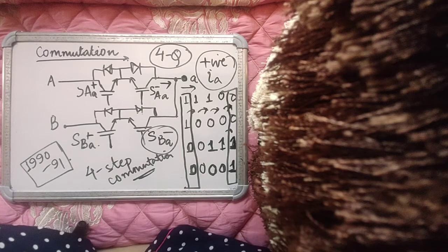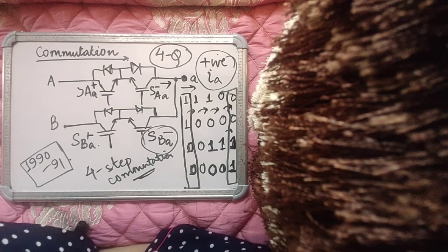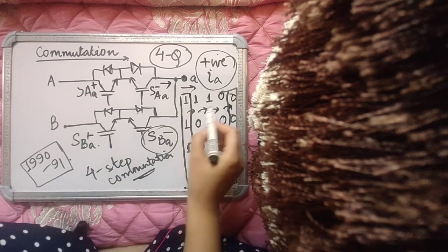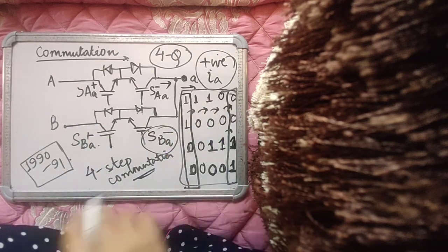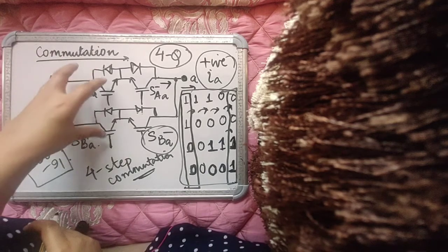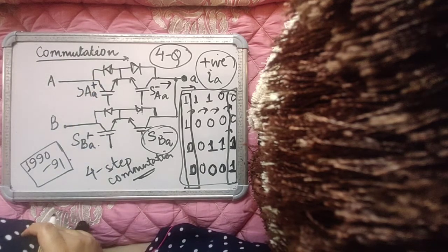These converters were not reliable because they had to be provided with extra protection through snubbers or clamping circuits, because the commutation was not safe. There were high commutating voltages involved, L di/dt kicks during commutation, and therefore once this commutation problem was solved through 4-step commutation, it became easier to implement bidirectional switches in such circuits.